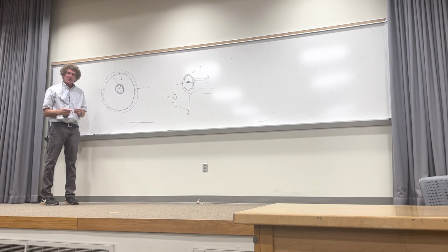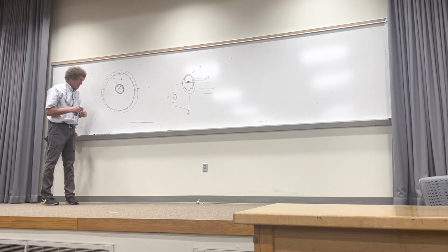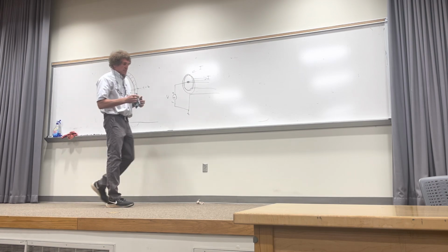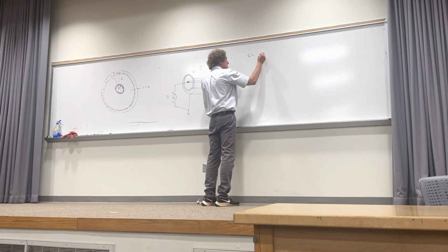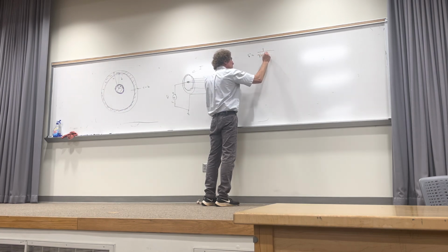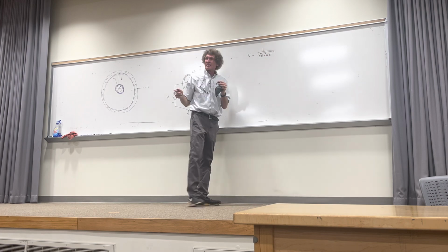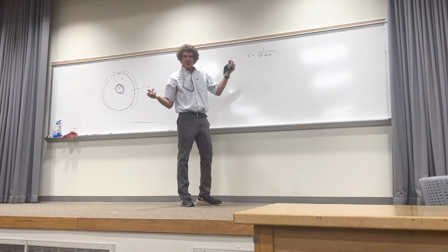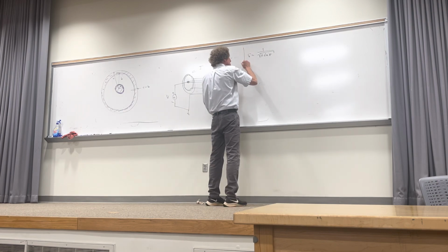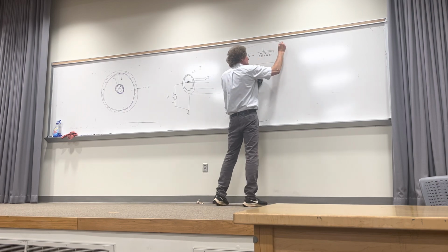So if you're calculating the resistance per meter of this problem, first you've got to do one calculation. First thing, you calculate the skin depth, which is 1 over the square root of pi f mu sigma. Did I put that down or not? I put 1 over alpha. All right, 1 over alpha, where alpha is this. So this is the definition of skin depth right here. This is the big one.